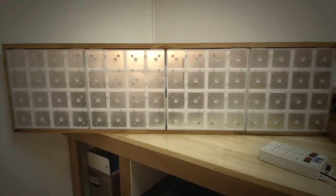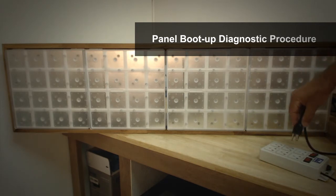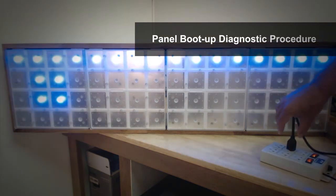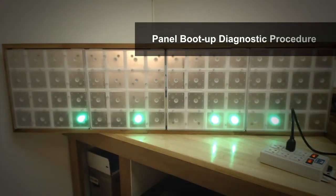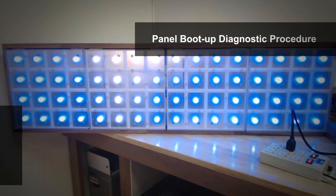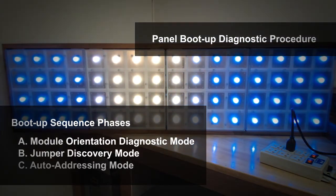If none of that seems to be the problem, we need to take a closer look at your actual Sensacell panel. To diagnose panel configuration problems, disconnect the USB adapter from your computer, close Sensacell, and manually cycle the power on your panel. Watching the panel go through its boot up process will help diagnose any problems that relate to module defects, incorrect orientation of modules, misplaced or missing jumpers between the modules, and several other issues. There are 3 phases to the boot up sequence.